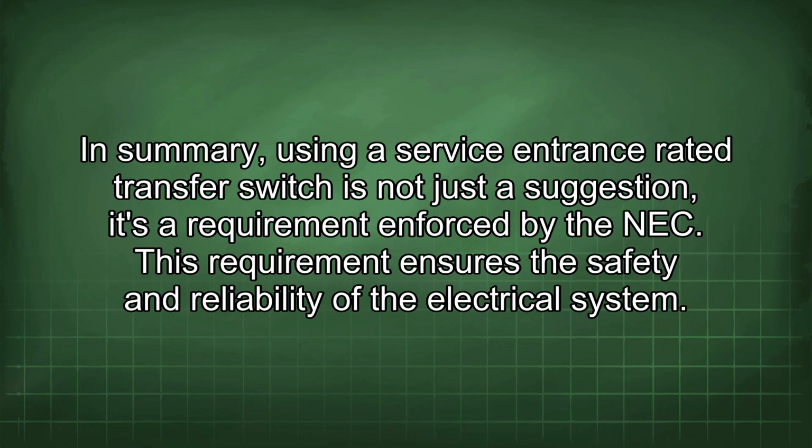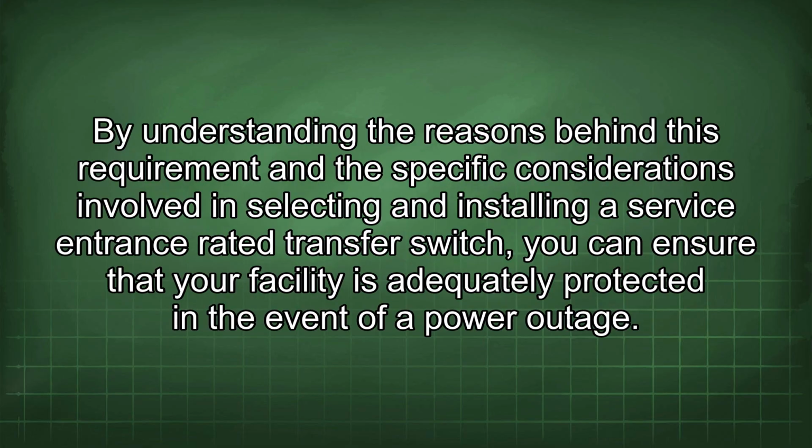it's a requirement enforced by the NEC. This requirement ensures the safety and reliability of the electrical system. By understanding the reasons behind this requirement and the specific considerations involved in selecting and installing a service entrance rated transfer switch, you can ensure that your facility is adequately protected in the event of a power outage.